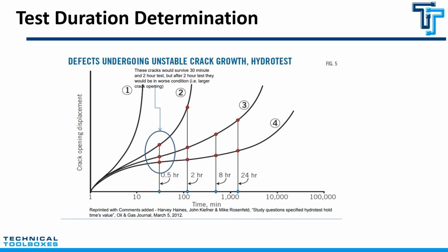Yes, we can. The only caveat there is you are essentially defining those begin station, end station, and the min and maximum elevation from an above ground specification at that point. And as long as you're defining it the right way, the tool should be able to handle that. Well, there's another consideration, which is the temperature. If you've got a sunny day and the pipe is above ground, that's going to present some problems.